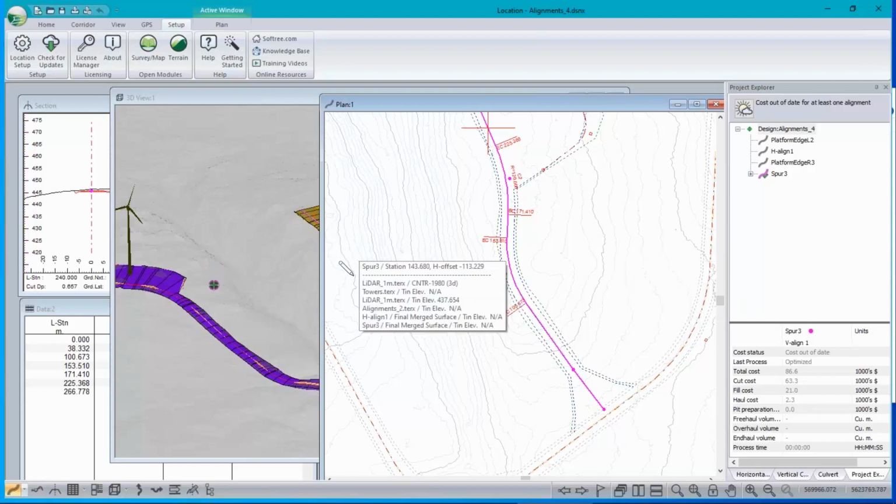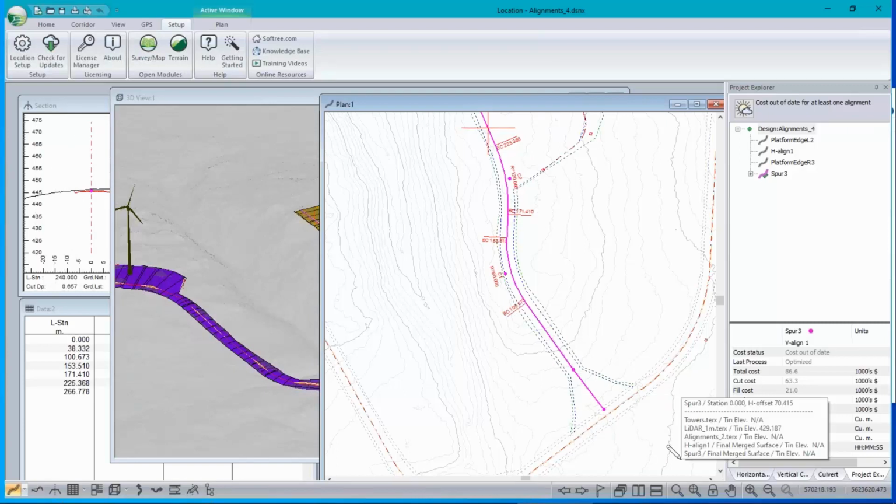There are some tools. One thing you can do is export this as a feature and reverse it in terrain and then re-import it as an alignment, but then you lose all the things like the templates and widenings and curves, and it's just not very satisfactory. The good news is we are working on a reverse function, but I really can't say how long it will take before it's ready.